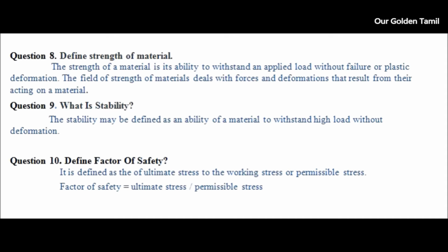Question 10. Define factor of safety. It is defined as the ratio of ultimate stress to the working stress or permissible stress. Factor of safety equals ultimate stress/permissible stress.